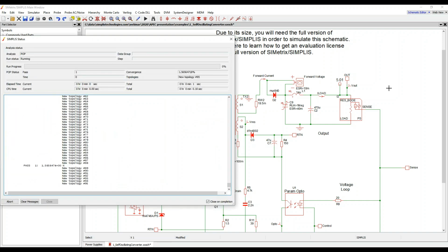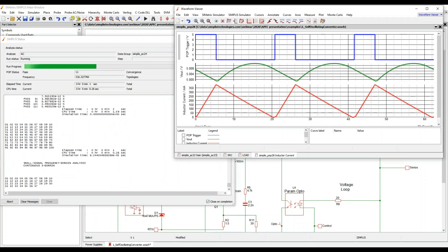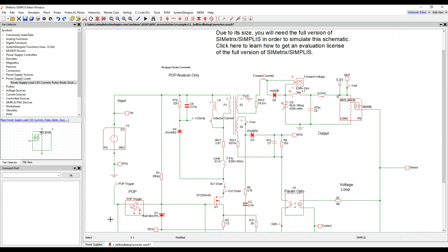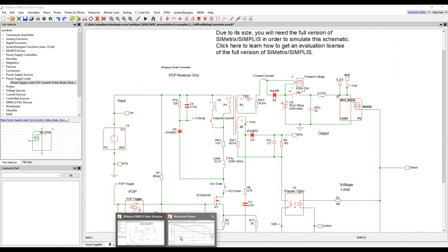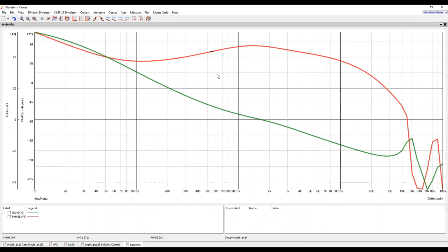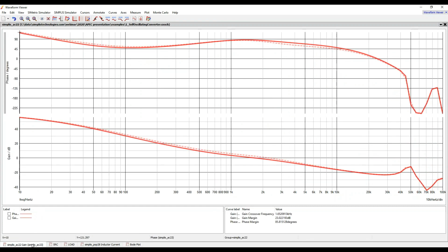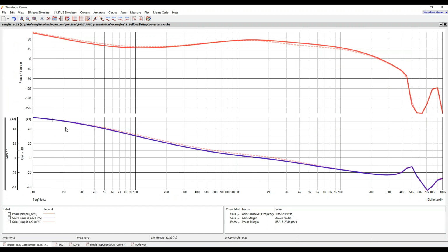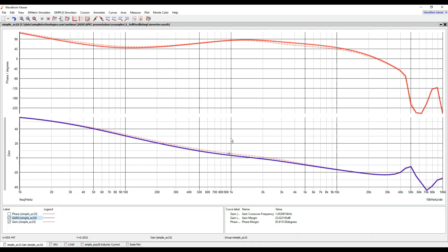Let's go ahead and run another AC simulation. And what we should get is exactly the same information as we did before. So let's go ahead and open up this guy. Now, because this Bode plot probe has different settings, it's going to appear on a different graph. So I'm just going to select this gain curve, do a Control-C, come back to our original graph here, and paste it on top of that. Let me make sure all of these are on the same axes, and there you go. You can see that it overlays nicely.